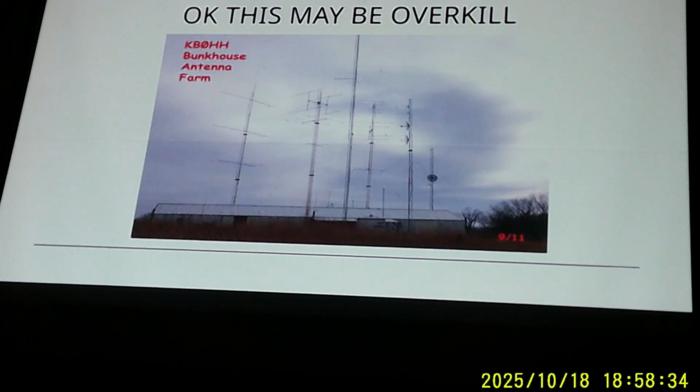If you get all those antennas, now, this is a little bit more than basic, but they're supposed to be a certain distance apart, and there's a math formula for that. Put them a certain distance apart, both vertically and horizontally. The coaxes all have to be the same length. You probably will feed it into a duplexer or something like that, so you only have one going to your radio. But you have to have everything just right. But when you have it just right, if you get 6 dB gain off of one, well, you're not going to get 12 off of two, but you might get 9.